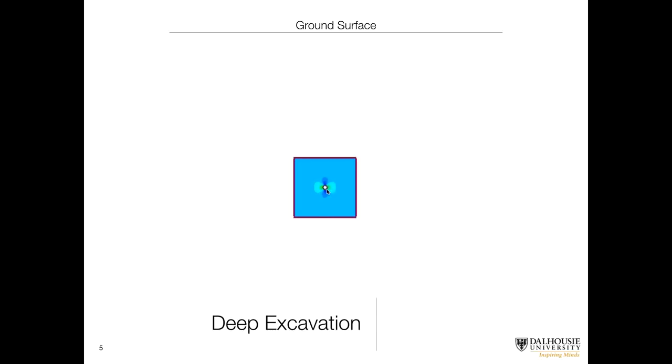So in reality, including the gradient due to gravitational loading in this simulation is really negligible. The couple of tens of kPa have little effect on the stability relative to the several MPa of stress that we're going to have on this tunnel. And so we usually neglect it and just use a uniform stress field. So the same horizontal stress across the whole domain and the same vertical stress across the whole domain. And that is an efficient way to get a suitably accurate solution.